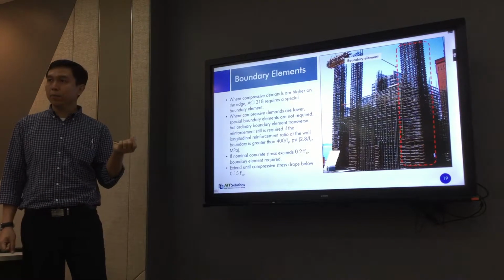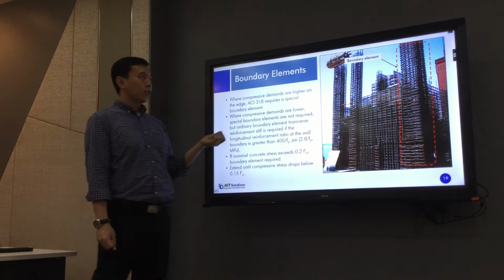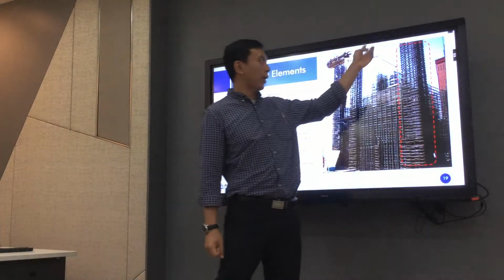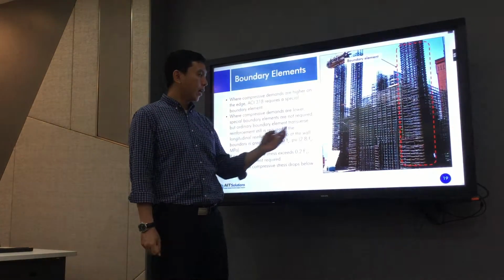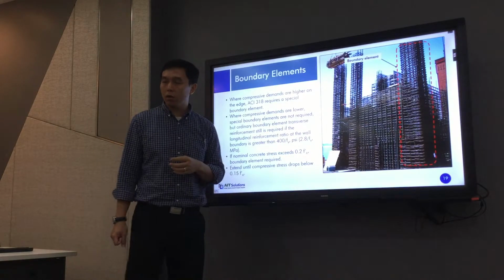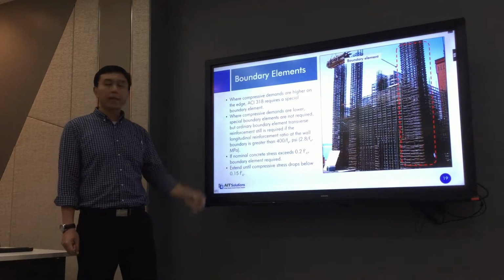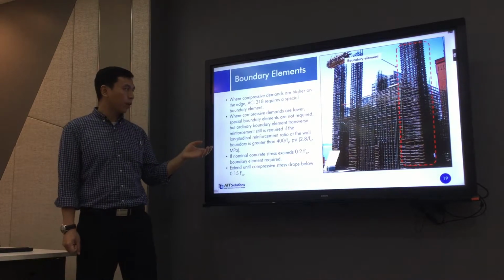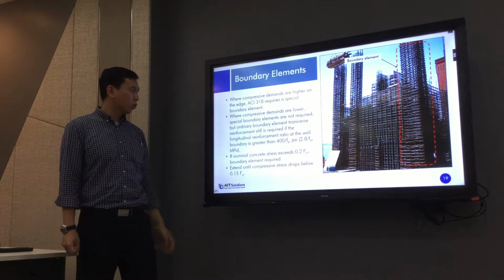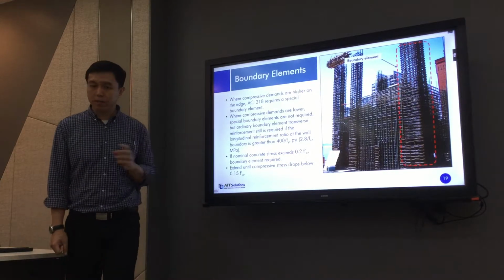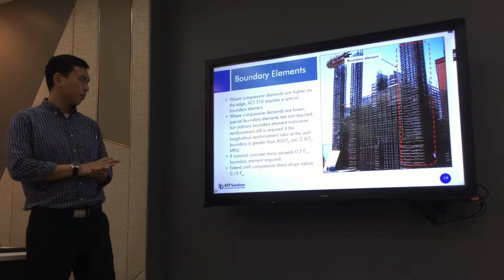In the displacement method, you have to check the displacement at the top of the wall, but that method will work for planar walls. For complicated wall configurations, I recommend using the stress-based approach.